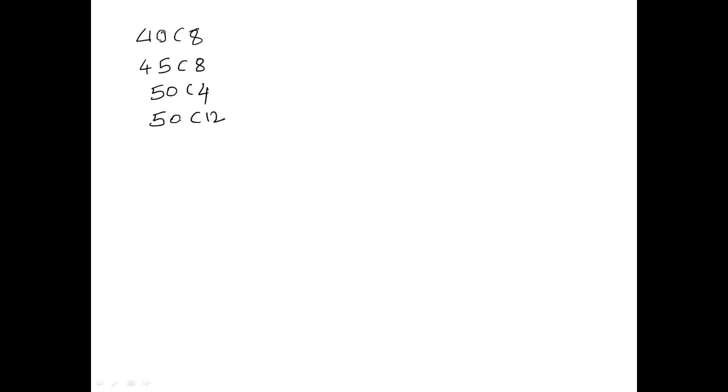When high strength is required, an alloy steel such as nickel chromium or chrome vanadium steel may be used. These are the carbon steels with 0.4 percentage, 0.45 percentage carbon with some alloy factor. So the normally used materials listed here are carbon steels of grades 40C8, 45C8, 50C4, and 50C12.